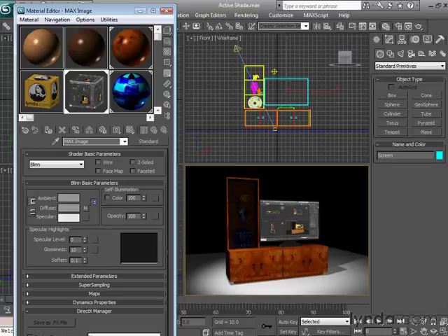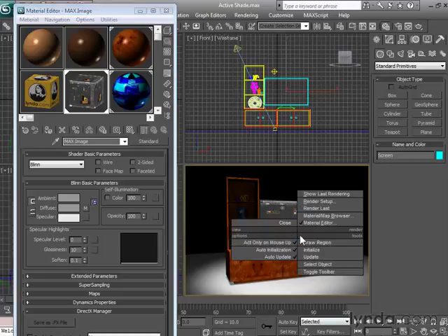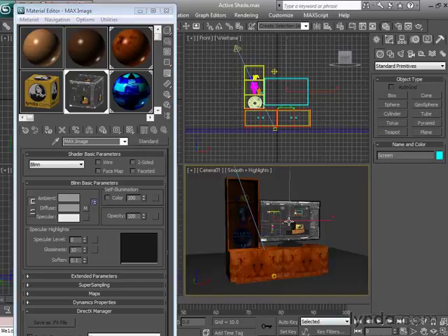One of the drawbacks of using the Active Shade viewport is the fact that you have lost one of your working windows, basically down now to only 3 views to physically manipulate the objects in your scene. When that's a problem, you can instead use a floating Active Shade. Let's first close the one in the view by putting our mouse on that viewport, right-clicking, and then choosing Close.